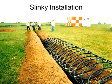And you can see by looking at this that it is important that you do have some means of ensuring that the soil is back into the trench, and that the pipe is surrounded by soil and not by any air. Phil Albertson, who's been in this business a long time, will tell you that the amount of soil that's left on top of the trench is the amount of air that you left in the trench. So use the wise sayings of Phil Albertson in your application.